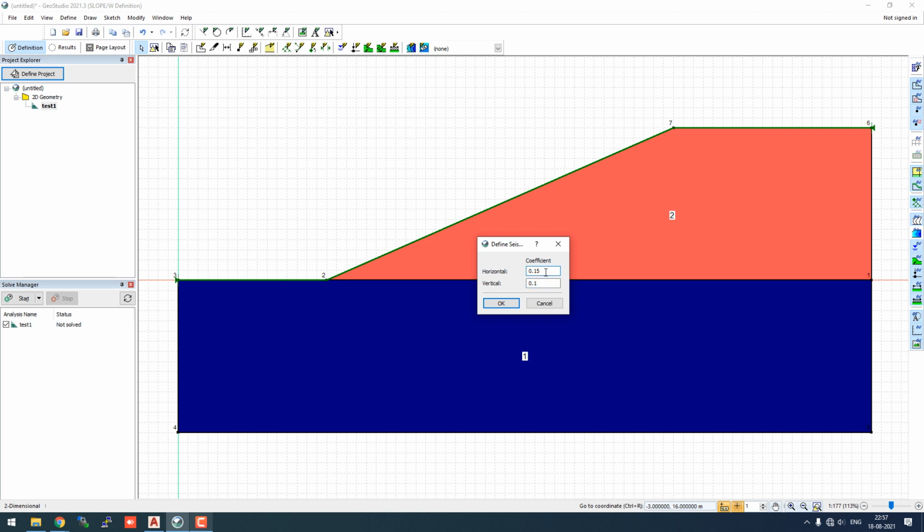So one more thing I would mention here is that you can calculate this horizontal and vertical seismic coefficient based on location or seismic zones in which our country India has been divided. But if any foreign standard or other standard requires you to calculate it differently, you can follow that. Basically in Indian Standard 1893 Part 1, you can look up the seismic coefficient definition based on structure as well. So now with these dummy values we can move on and start solving our problem.